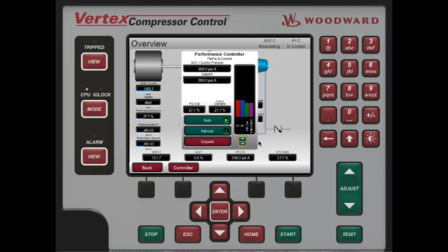And here I can increase the set point, so if I need to come up a little in pressure, I can do that from here. I can also go back into manual control, and that will hold at the last position. You can see that transition was bumpless. And now I'll go ahead and increase the valve demand and go back now into auto, which will control it back down to the set point that you had in there.